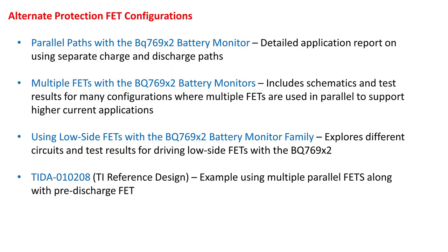We will show a couple more examples for FET configurations, in which we will not go into great detail, but I first want to point out these important resources for different FET configurations. For the case where separate charge and discharge paths are needed, you will want to refer to the Parallel Paths application report, which includes example circuits and test results. For the very common case where multiple FETs are needed in parallel to support higher current, the Multiple FETs application report is a very helpful document that includes the circuits and test results for many configurations.